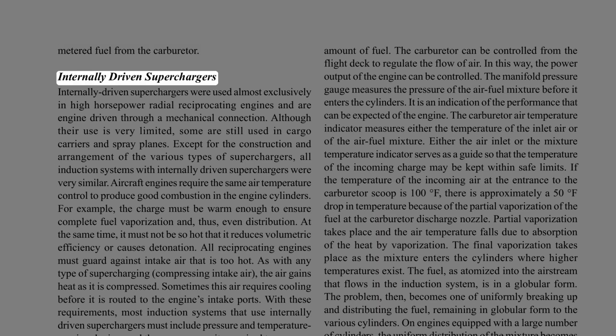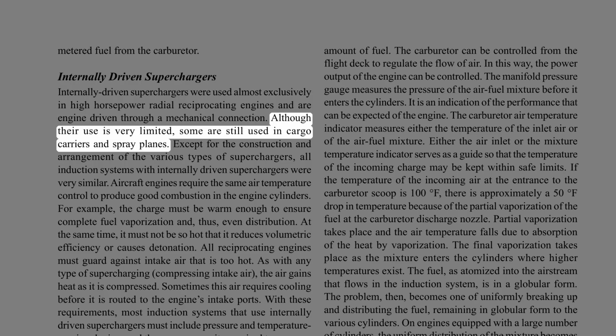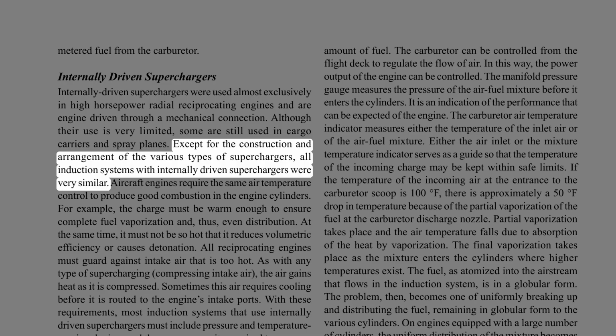Internally driven superchargers. Internally driven superchargers were used almost exclusively in high-horsepower radial reciprocating engines and are engine-driven through a mechanical connection. Although their use is very limited, some are still used in cargo carriers and spray planes. Except for the construction and arrangement of the various types of superchargers, all induction systems with internally driven superchargers were very similar.